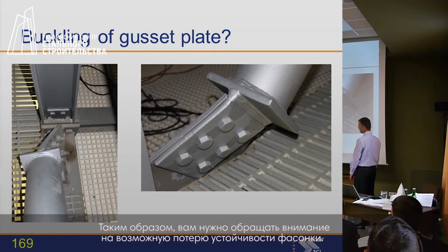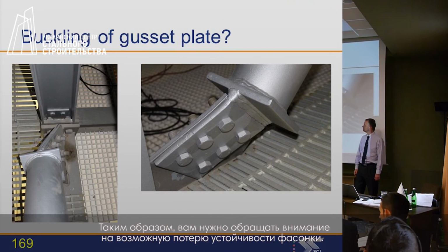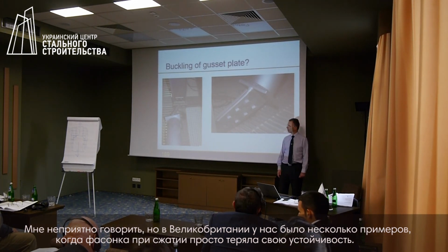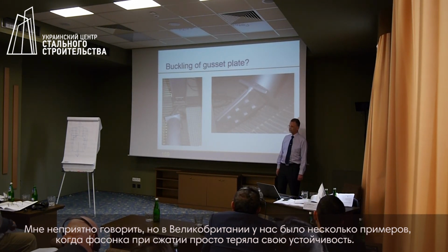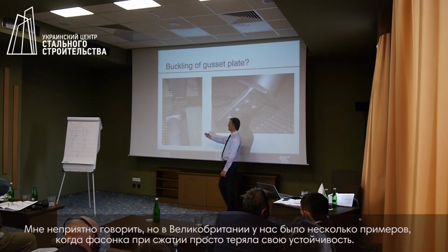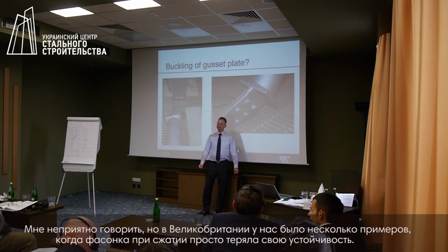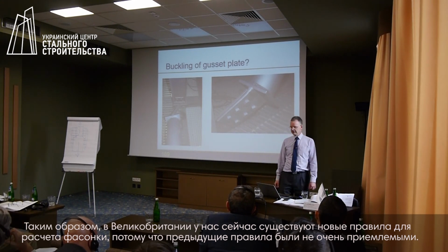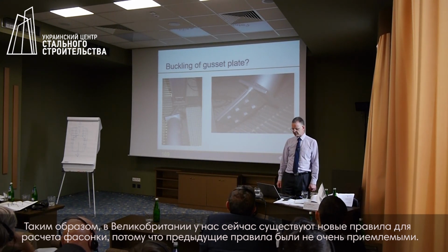Because I am afraid to say in the UK we have had a couple of examples of the gusset plate in compression buckling. So in the UK we now have new rules for the design of the gusset plate, because probably our old rules were not adequate.